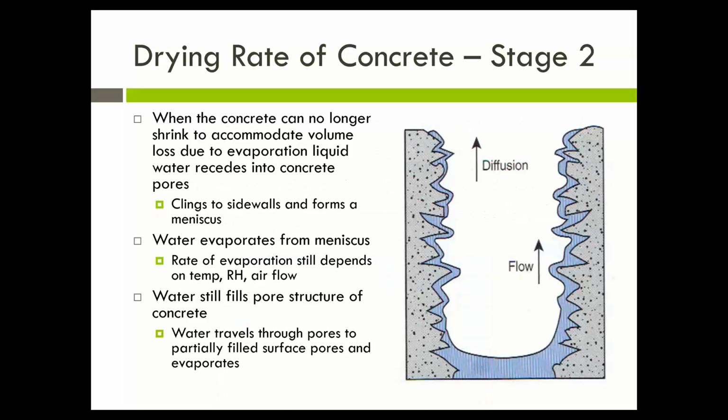In the second stage, after the surface water can no longer shrink to accommodate for that change, we are then going to see the water in the spaces in the concrete, in the pore spaces, flow to the surface and evaporate. And you will get a meniscus, just like you would from a straw that's sitting in water or any other capillary, where the water will evaporate and that meniscus,